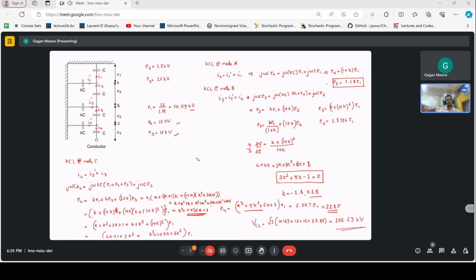We can increase the string efficiency by adding that guard wire. Then there is one more capacitor here. There can be one more here also. So then in KCL, one more current will come here, and that will be like this. So to remove the effect of this capacitance, if we cancel these two, then current is same.